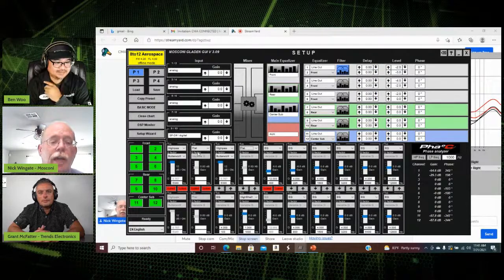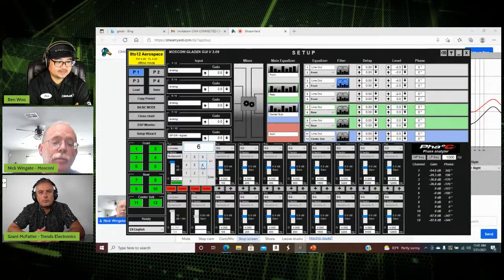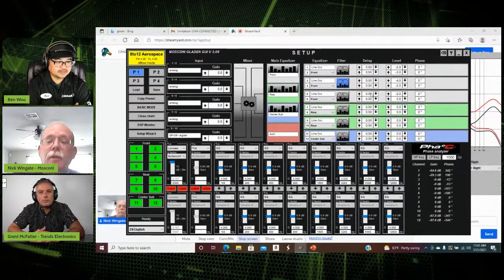Now notice that we have a 24 dB per octave slope high pass filter at 6,300 hertz. I'm going to build a low pass real quick at 12 dB, and we're going to make it 6,300 hertz. So this is a two-way. Now, these drivers are not in phase with each other exactly because of the slopes we chose. I chose a 12 dB and a 24 dB. They are not perfectly phased with each other.